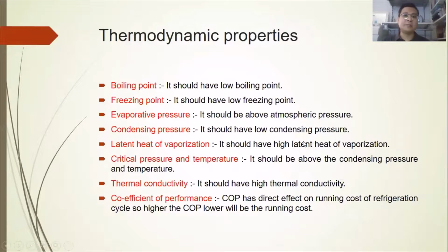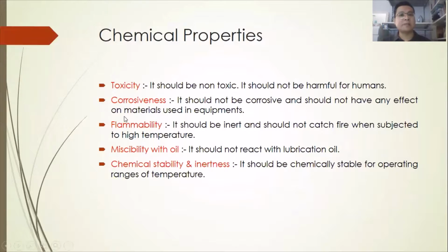Then COP performance is good. And then we go to chemical properties. When we select refrigerants, they should be non-toxic, so we satisfy all these parameters. And then not corrosive, not flammable or low flammable, miscible with oil but should not react with the lubricant oil, and chemically stable.